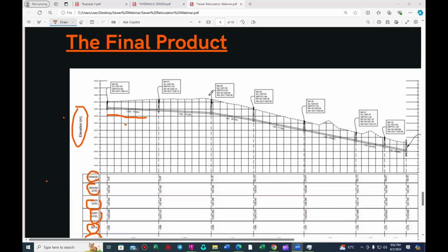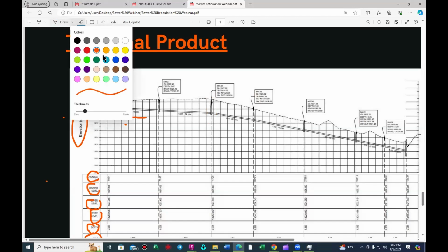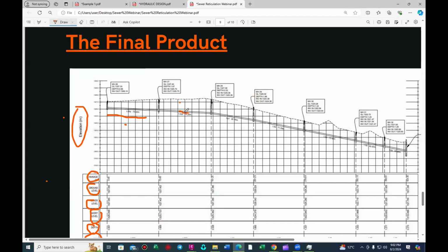Another thing that you need to understand, guys, about manholes is that they act as a temporary storage. What happens is that your sewer is flowing and it's full in this pipe, right? Assuming this pipe is overwhelmed, it's full. So when it gets to this point, the sewer will start rising in the manhole here. So the manhole can also act as a temporary storage if the sewer system is overwhelmed, such that during peak times, the sewer levels will rise in the manholes because it's flowing at full bore, so there's not enough space for the sewer to flow.